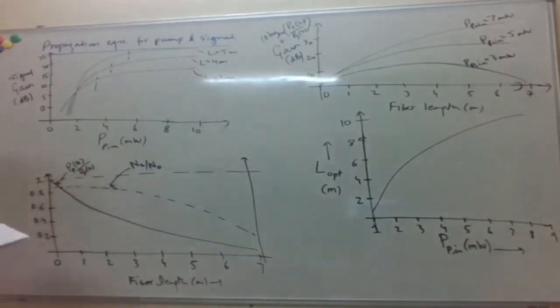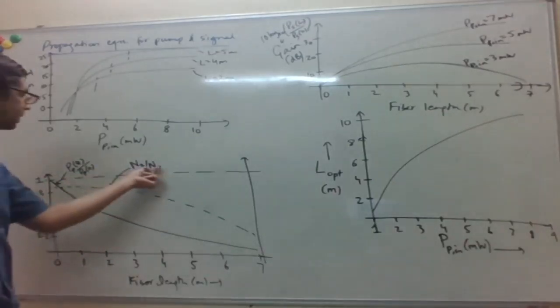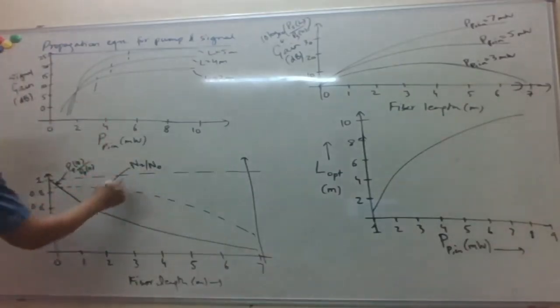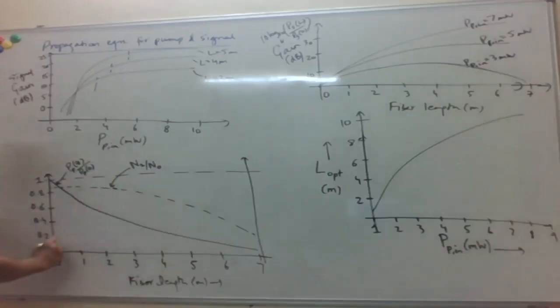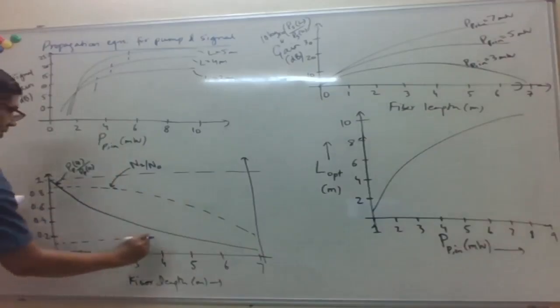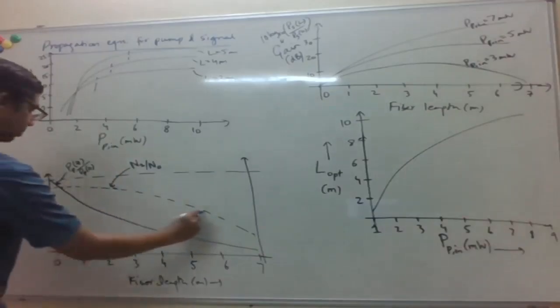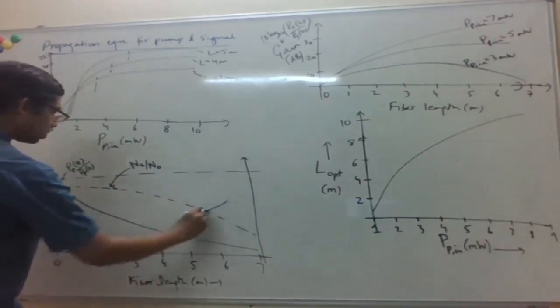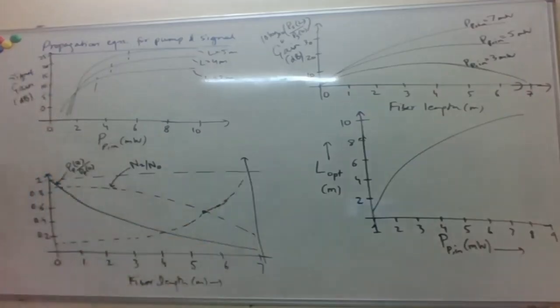pump power is high. Equivalently, now we can plot n1. Again, n1 plus n2 is basically just n0, so that is distributed between 1 and 2. So 1 minus this will just be n1. That looks like this. They'll cross at 0.5 here. So this is n1 by n0.